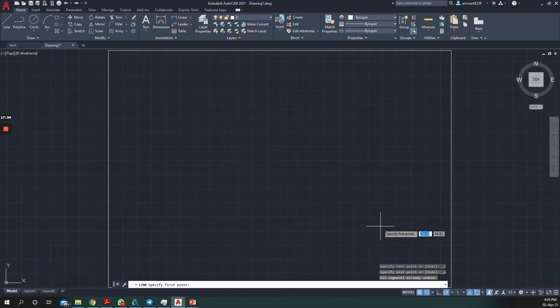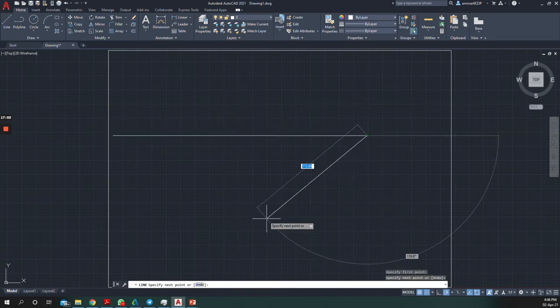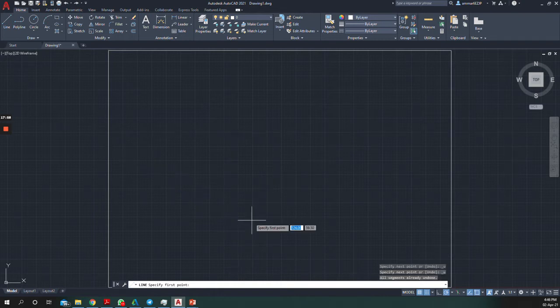Well, you first click on the line, LT scale. Let's increase it to 50 just to see the differences. Not much. Okay, not much. Okay, you can play around with that. Okay, LT scale. So the default would be 1.